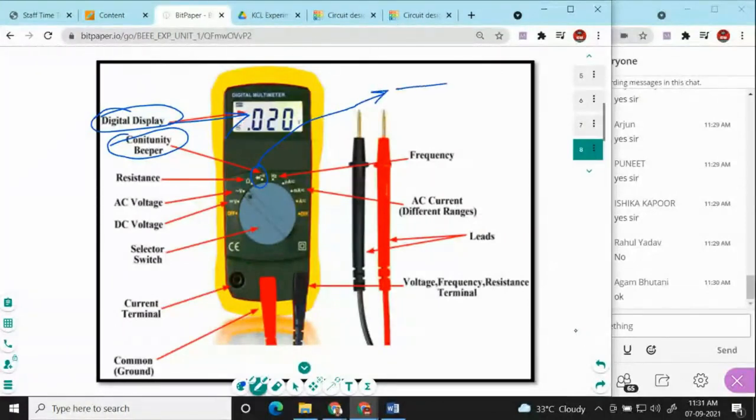Okay, let's suppose that this is our wire, and this particular wire is broken at this particular position. Okay, so how to check the connectivity? You have to connect one ground position to one terminal, and you have to connect positive to the other terminal. This is terminal 1, this is terminal 2, but this particular wire is broken inside the insulation, okay.